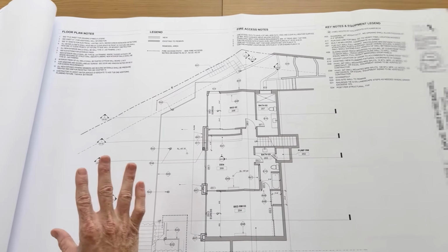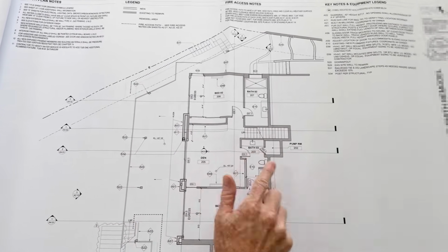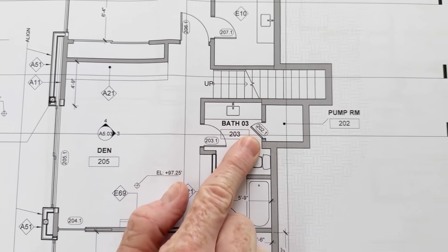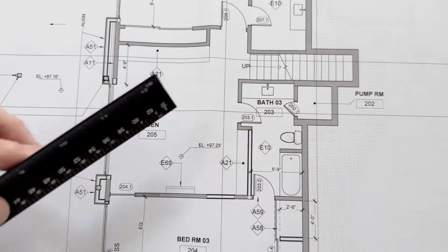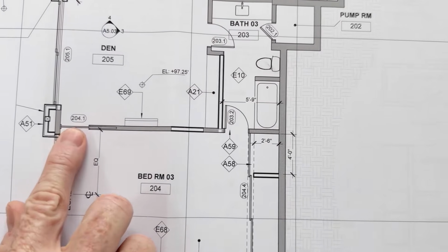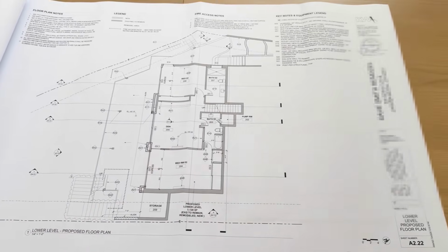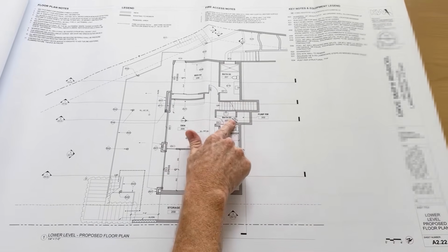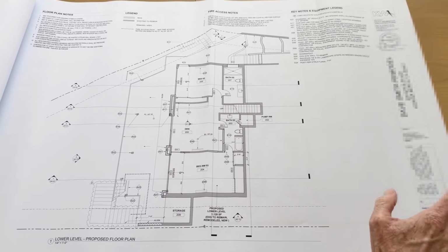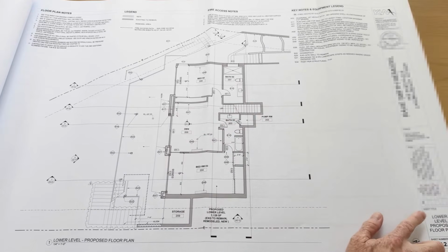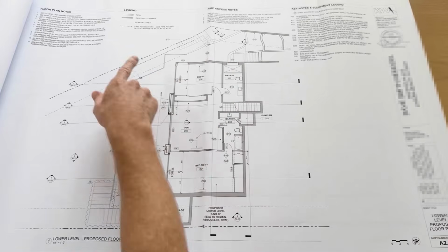Just take your time and follow the notes. These indications here on the proposed floor plan, as you can see, like 202.1, that indicates a door call out. So as you can see, it's right next to the door. We've got another one right next to that door, and another one right next to this door. So 204.1, when you're trying to do your door takeoffs or figure out how big and how much to order our doors, there's a door and window legend, which we'll get to a page, and we just cross-check and make sure that we're following whatever the legend is telling us is going to be installed on that plan, okay? Or on that section. So lower level proposed floor plan, again, just follow the notes.